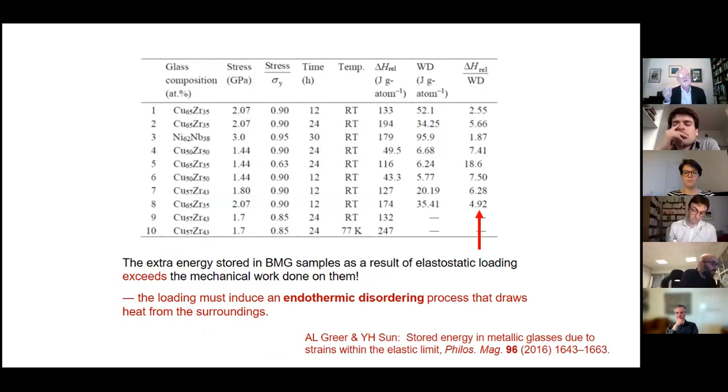And that fraction might be between 1 and 10%. Well, in this elastic loading case, it's not totally elastic. There's a tiny creep strain. It's rather easy, you know the stress very straightforwardly, you know that creep strain, to work out the mechanical work done on your sample. It's also quite straightforward calorimetrically to measure the new stored energy as a result of that.